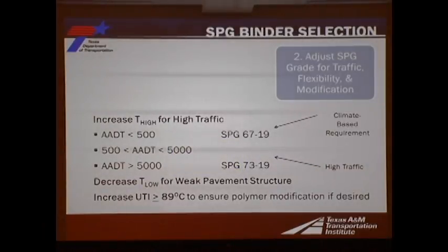Then you make adjustments, possibly. So just like with the PG spec before it, you look at your traffic conditions. And if you've got heavy traffic, a lot of curves or a lot of turnouts or something like that for a seal coat, and you feel like you need more performance, you can bump that grade up. You can widen that grade out to deal with the issues that you think you have. And in fact, most of the time we recommend that you do that.